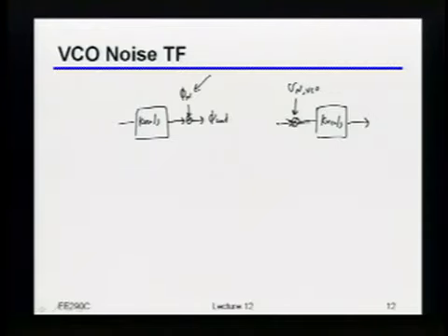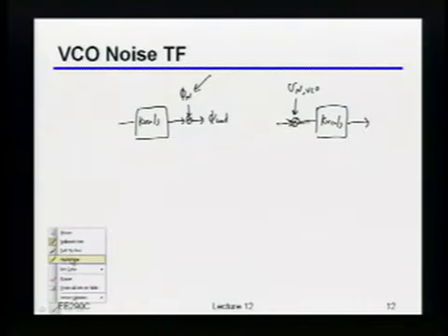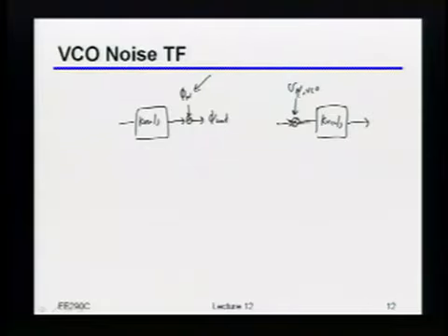So typically the way people model the VCO noise is to figure out the equivalent voltage noise going into the control port of the VCO. Because if you know that, then life is pretty easy. There are no infinite quantities anywhere that you have to deal with. You just have the spectral density of the thing causing the jitter in the VCO.